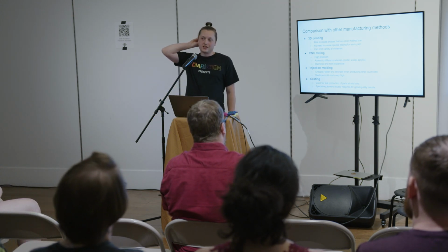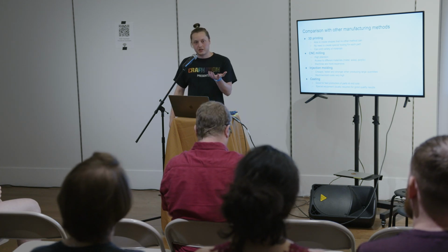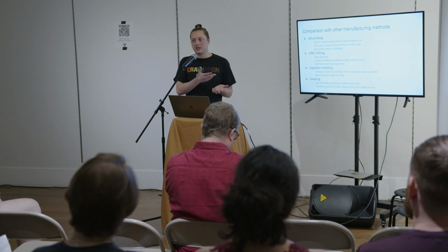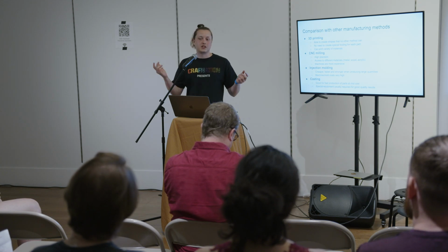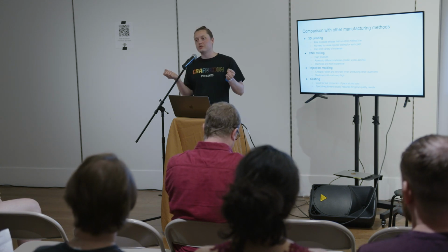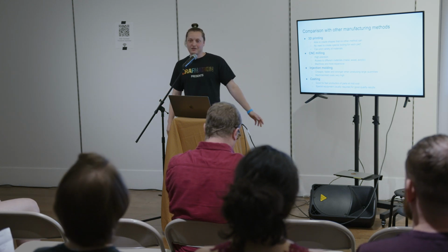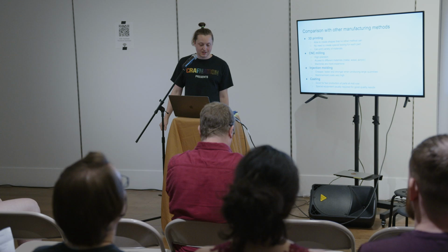Injection molding is awesome if you want like 100,000 of a part. Otherwise, the cost to machine those molds, get them finished and ready for injection molding, can be anywhere from $10,000 to $30,000 per mold, which is a huge upfront investment. If you're not selling hundreds of thousands of parts, it's not really worth it, and that's where 3D printing is great.